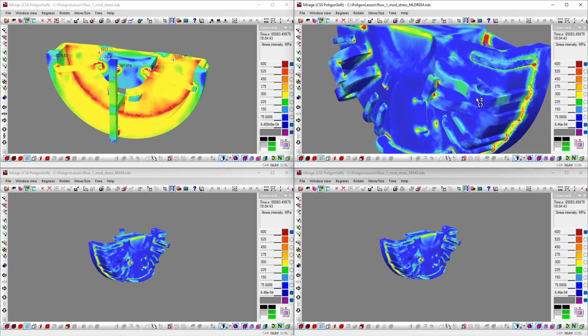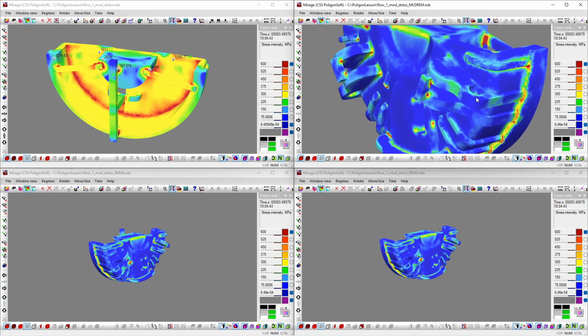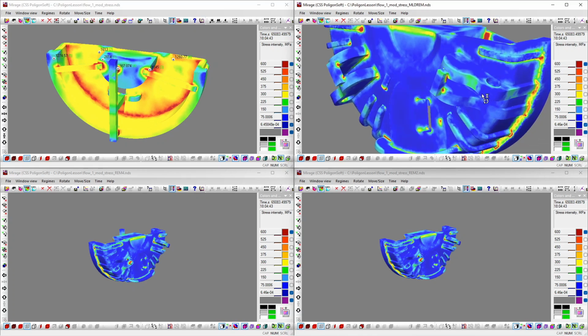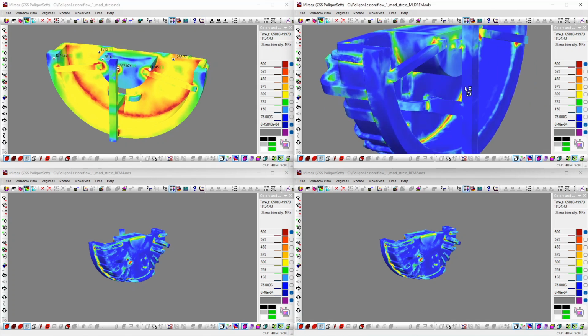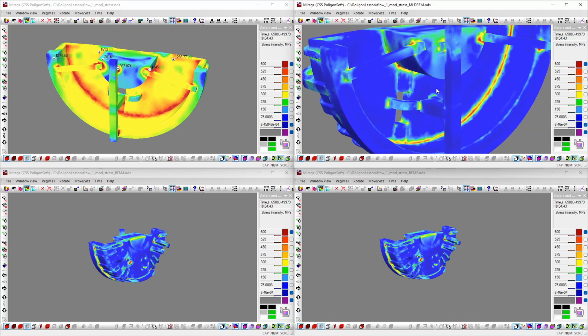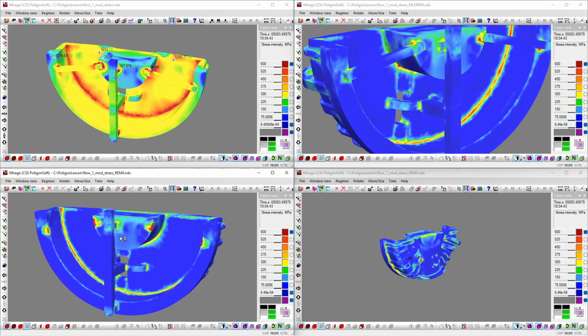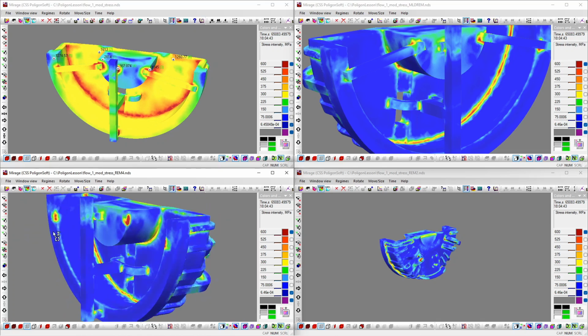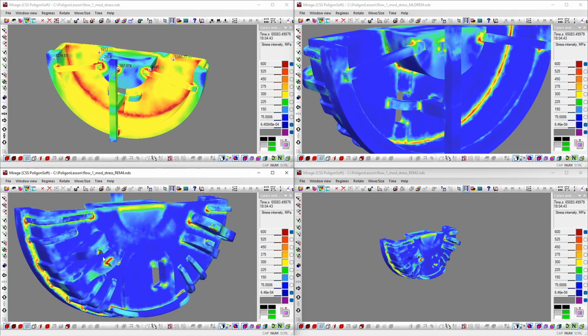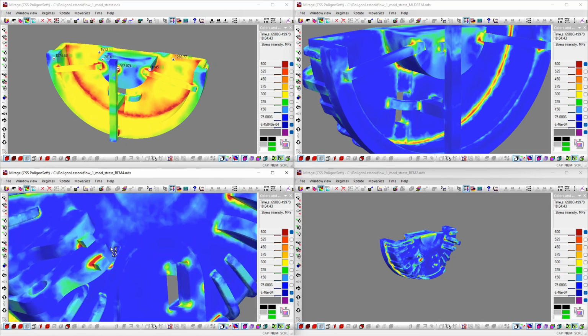The plastic properties of the alloy change significantly at high temperatures. As a result, if we had stopped the calculation not at 500 degrees, but, for example, at the solidus temperature, the picture would be the opposite, since the stresses at temperatures above 1000 degrees will be significantly lower than when the part has already cooled down. The removal of the gating system did not significantly affect the pattern of our stresses. In our case, the removal of the gating system will not cause any additional problems.